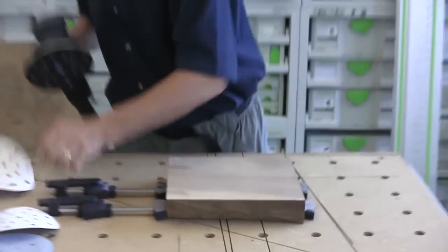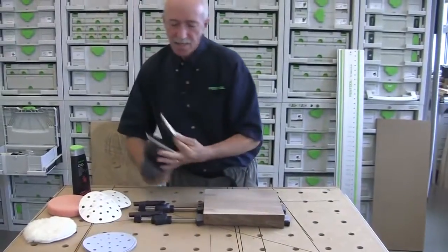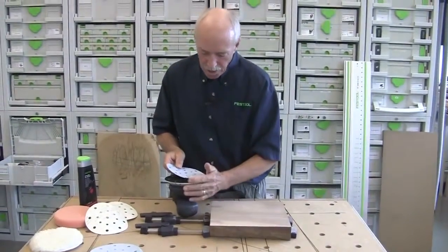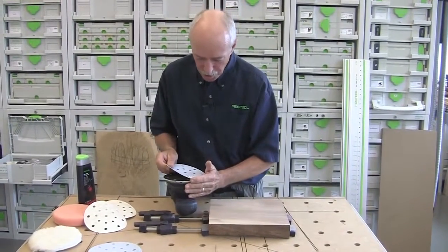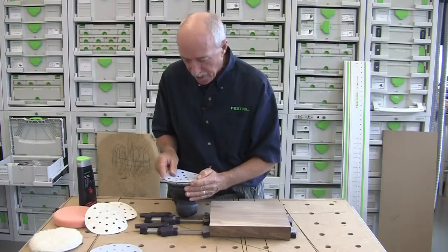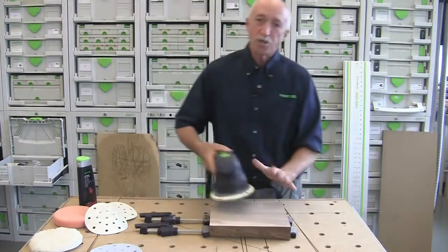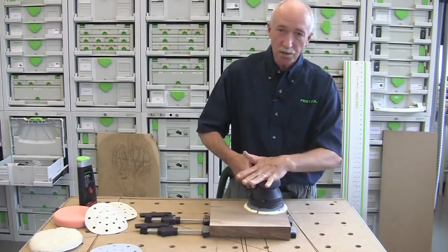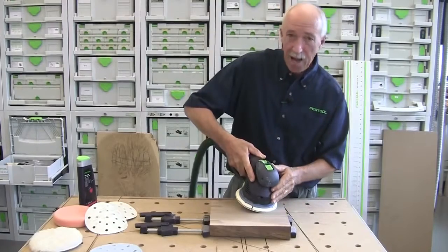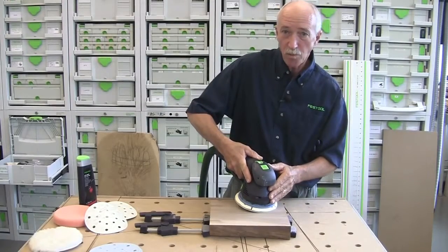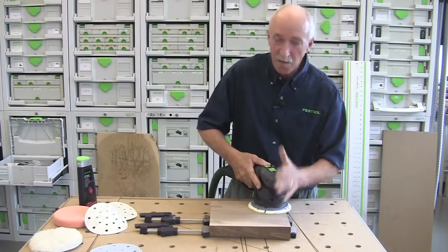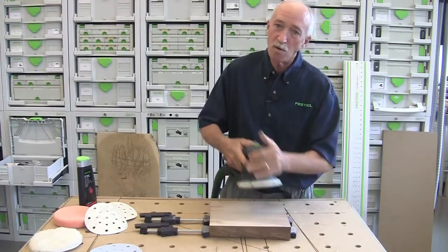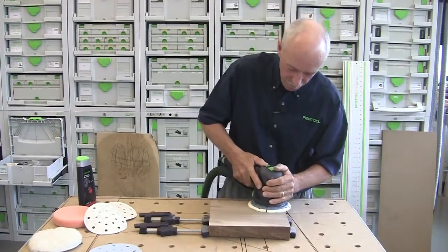Now, another thing that we've talked about in our training classes is the question, is it right to start your sander on or off the work? So as we do this next grit, which is now 80 grit, I want you to understand you should start your sander on the work, so you're not gouging into your work when you bring the pad to the work. So we start the sander on, and when we finish, watch, I'll remove it before I shut it off.